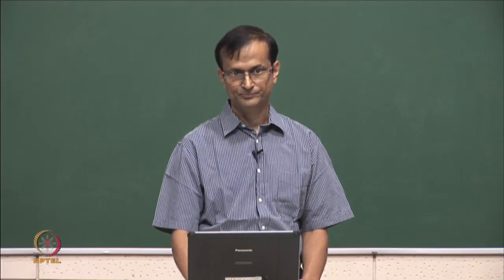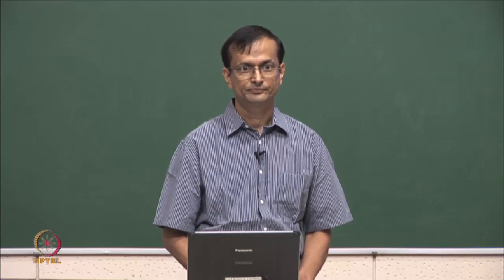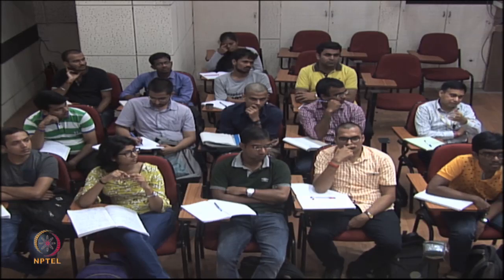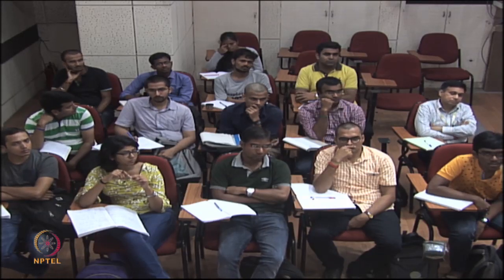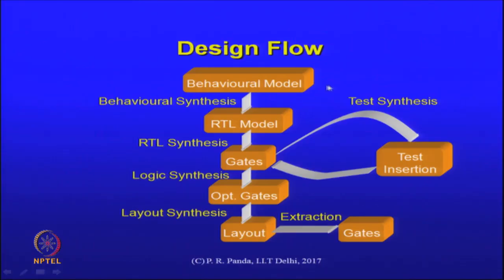So, the HLS, the high level synthesis which you are mentioning, how similar or dissimilar is it with the RTL level to gate synthesis? Oh, so we indicated that there is a behavioral synthesis and there is an RTL synthesis flow. These are different just because the levels of abstraction are different, the components, the objects, the properties, and all of these are different in some ways.